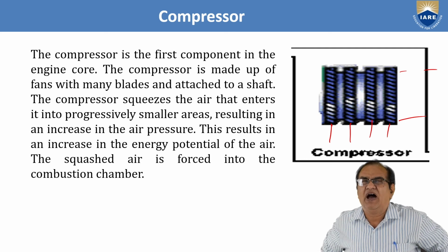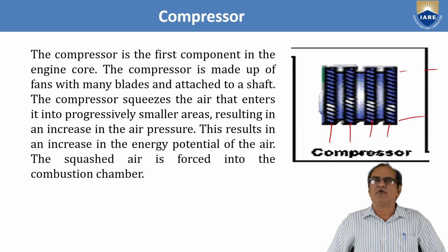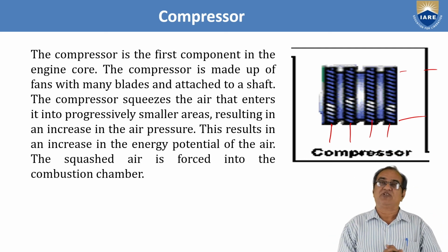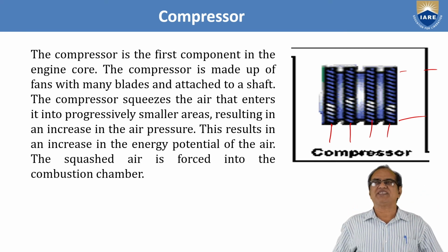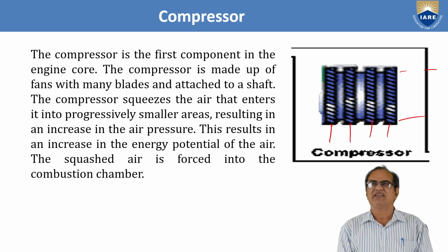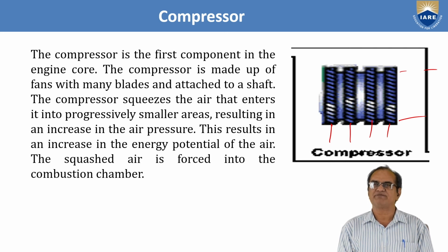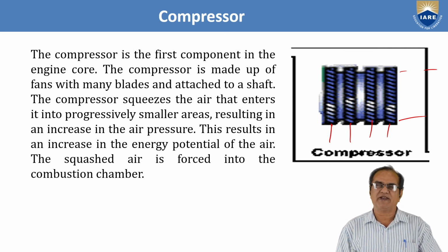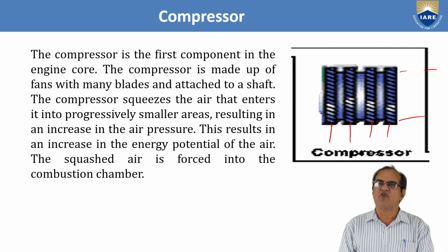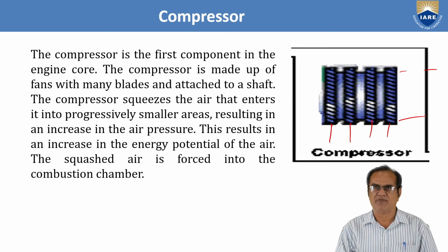So the compressor is the first component in the core of the engine. Your fan is not core, it is ahead of the core. The compressor squeezes the air that enters into a progressively smaller area, resulting in an increase in the air pressure. This results in an increase in the energy potential of the air. The squeezed air is forced into the combustion chamber.